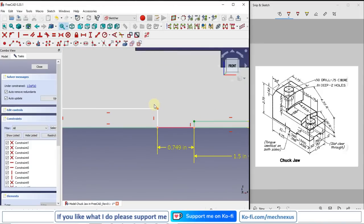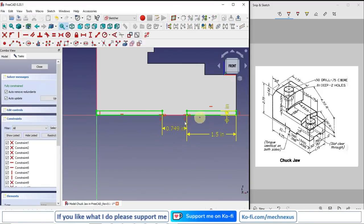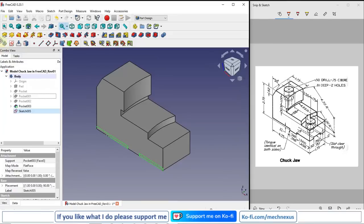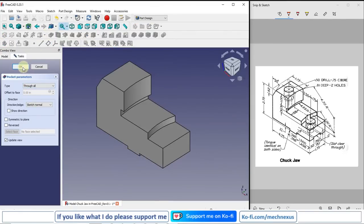Now I will select these 2 points and give it horizontal constraint. So our sketch is fully constrained, so I will close my sketch and I will go for cut, and then I will simply say through all, and I will say OK.